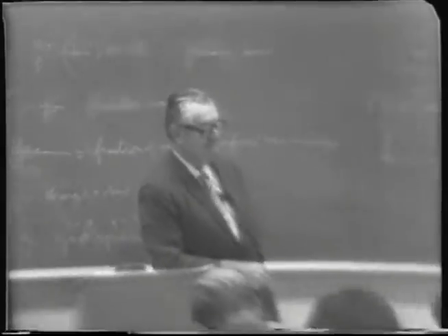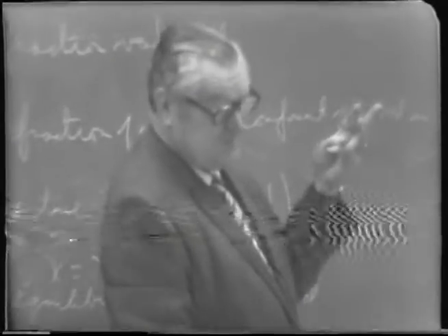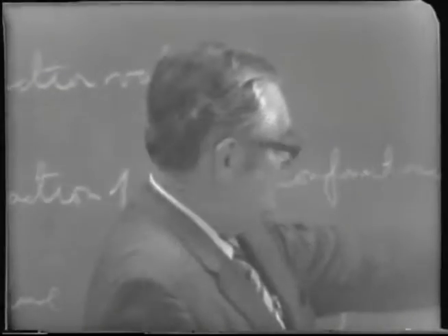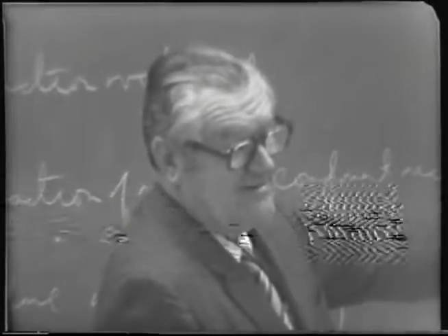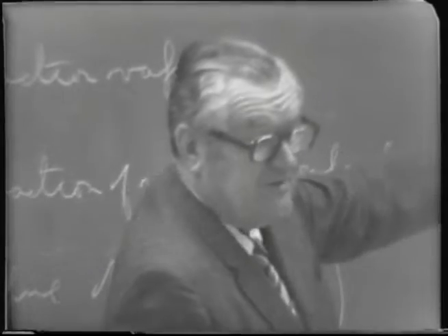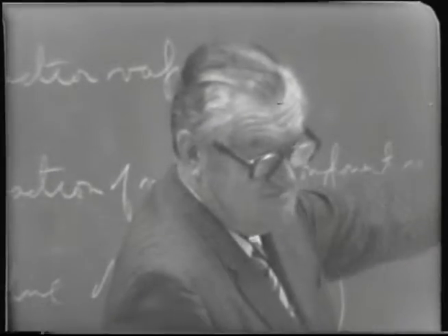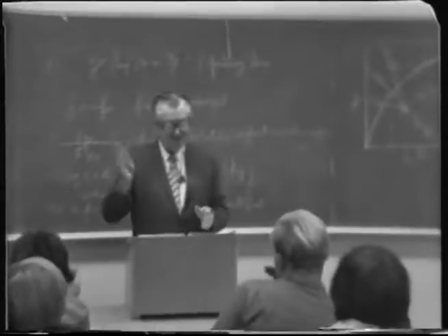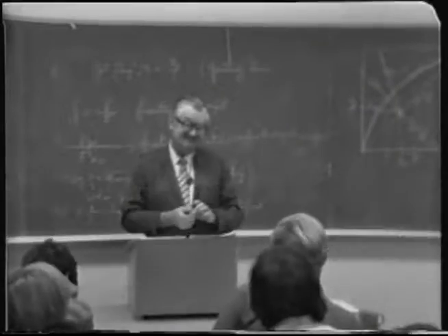Does each one of these lines with different slopes, when you just draw them there, define essentially a different operating condition? Yeah. The way I did it here, I drew 3 lines which represent 3 different operating conditions with respect to the amount vaporized. And of course for a constant value of x sub f, I didn't change that. So by different operating conditions, you mean the different amount of vapor when it enters that flash chamber? Well, the different amounts of vapor that's removed in reference to the feed rate. The fraction vaporized.